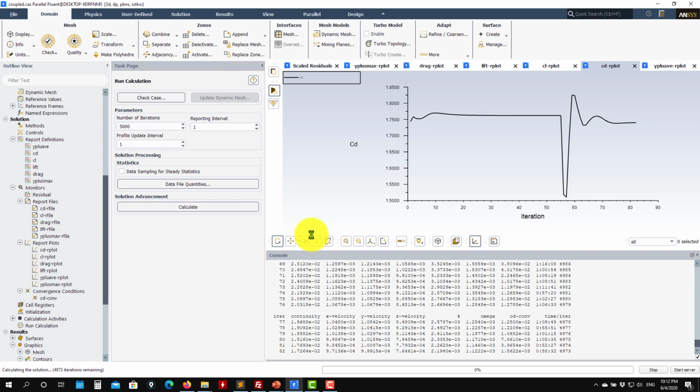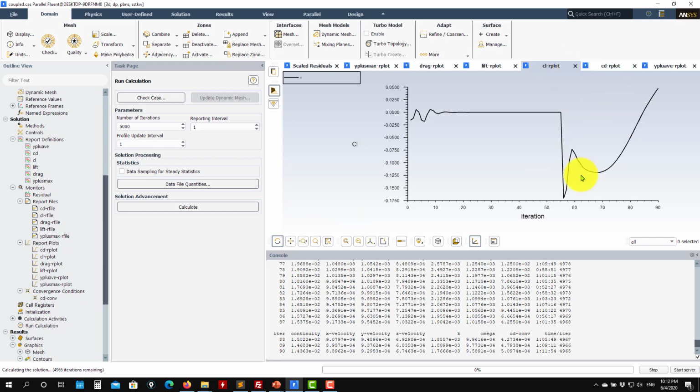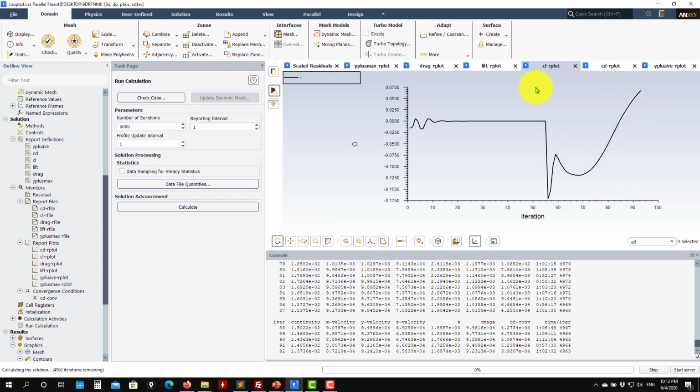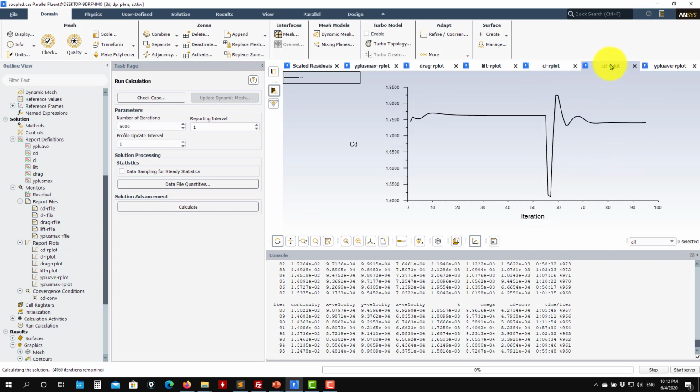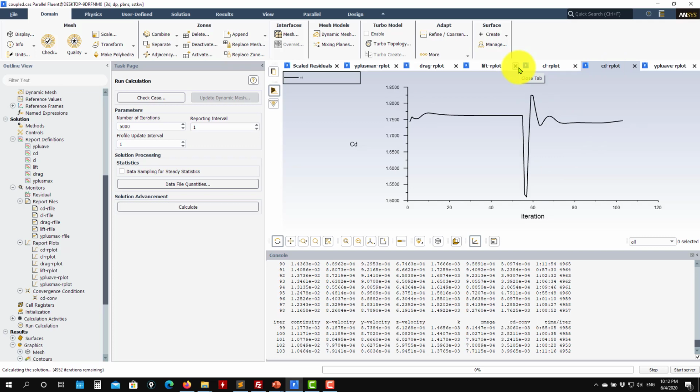And, maybe look at that, we are now seeing some oscillations. Okay, so probably we need to let it run. But see that, for instance, lift, it's not flattening like the coupled. So this is what I want to tell you, that doesn't mean that the coupled is wrong or the SIMPLE is wrong. Both of them, as they have different numerics, probably the coupled, as it is putting all those equations together, will reach that steady state faster, and probably it will reach a solution.